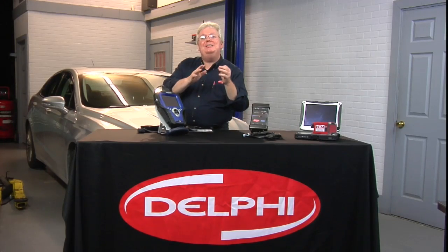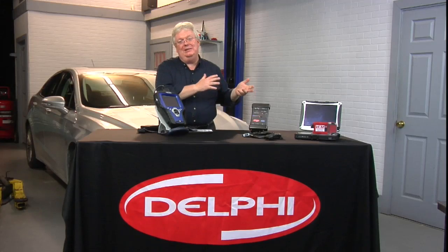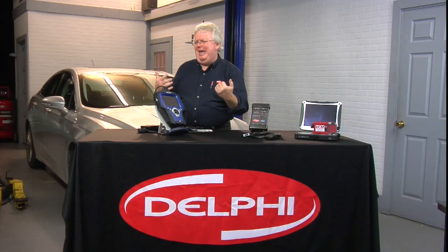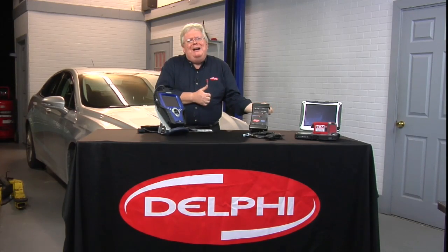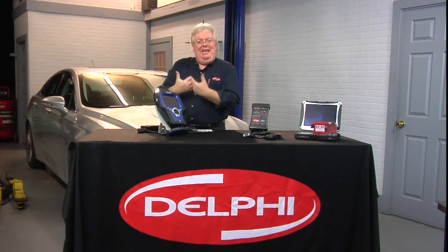And then, Christian, you've got the low-speed CAN buses. And then the buses that aren't even CAN, the local interface networks, LIN buses, and others that are just proprietary. They don't hook up to the DLC. Your scanner doesn't see what's going on, but they connect in with a bigger module, let's say a door module on a local bus, like a LIN bus connecting to a BCM. And then that's what you see on a low-speed CAN bus with your scan tool.